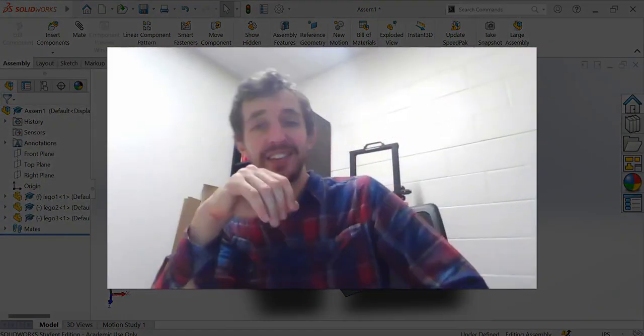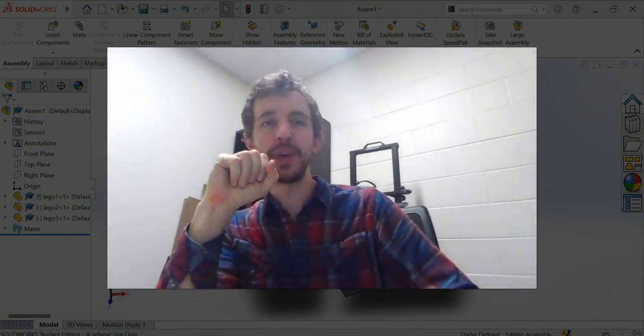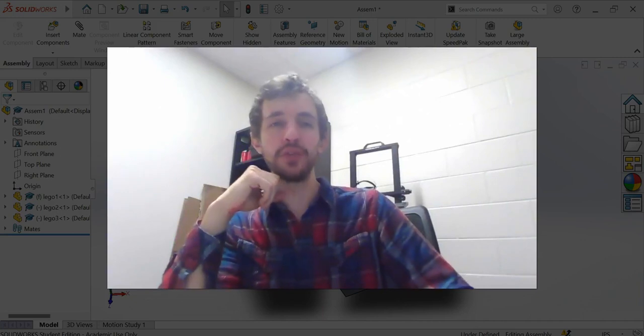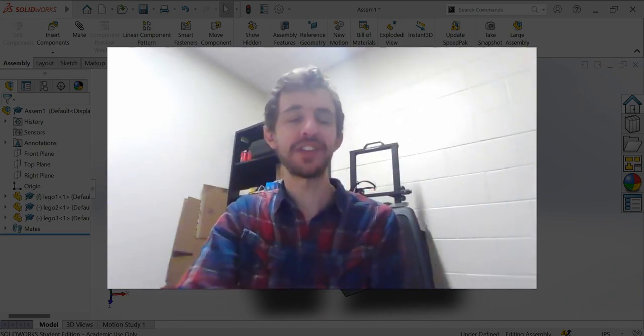Okay, everybody, so that's the last little bit here. I just wanted to kind of really dive deep with mates. Make sure you understand which ones are most important. Coincident, tangent, those are the workhorses. And also make sure you don't have that horrible, horrible mistake of accidentally fixing everything.